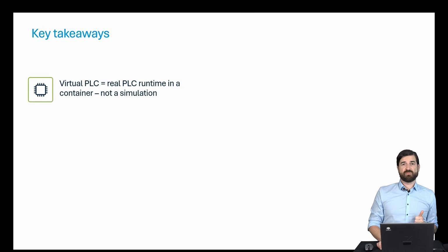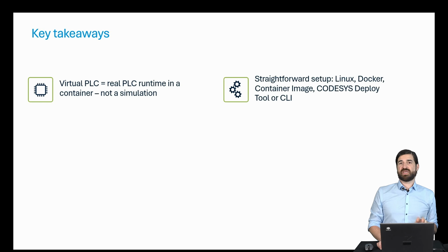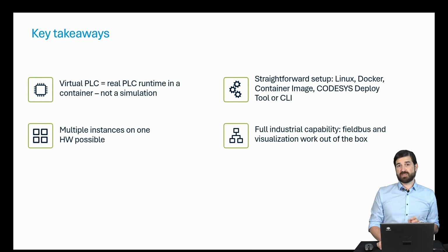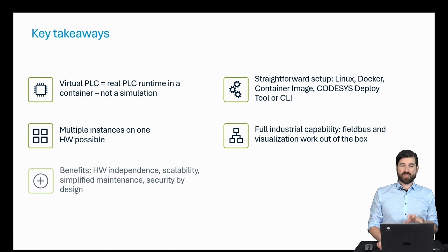A virtual PLC is a real runtime that runs in a container. It's not a simulation or a mere fantasy. It can be used in the real world, and it is. The workflow from initial setup to final productive operation is just straightforward. You can run multiple instances on a single piece of hardware. Full industrial capability is there from the start, for example, regarding fieldbus communication or visualization. And the benefits we've just seen aren't just future promises, they're already reality today.